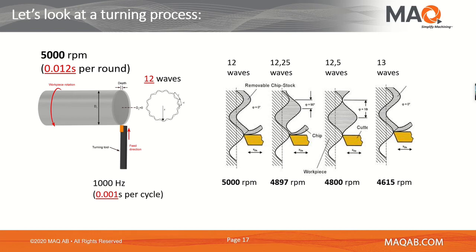They are in phase with each other. And we have a constant chip thickness that is being removed by the two. And that means we mostly have the static part of the cutting force. We don't have the dynamic force anymore because it's constant, theoretically.